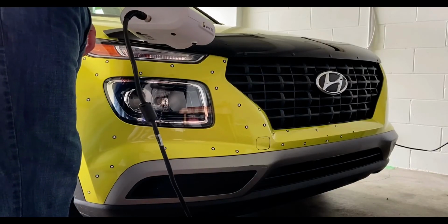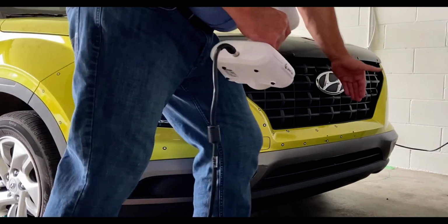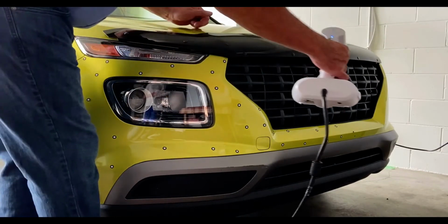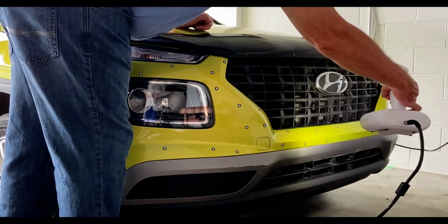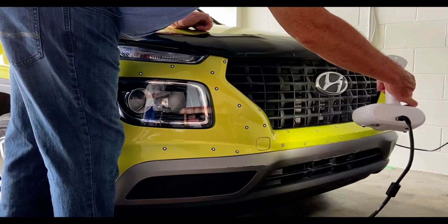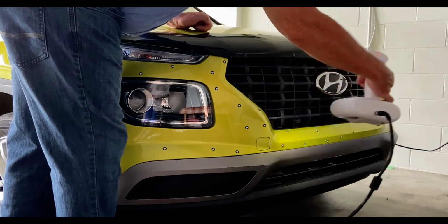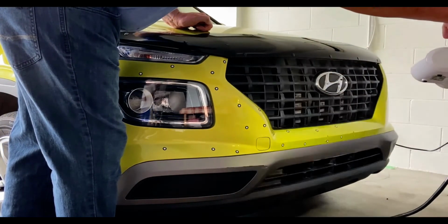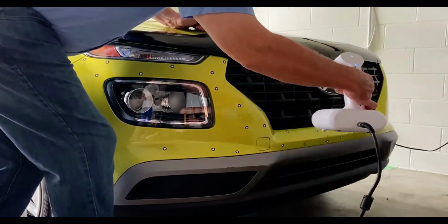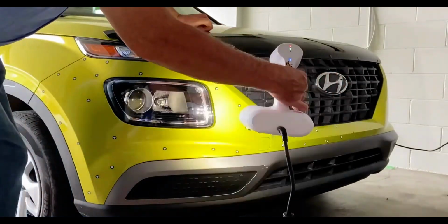We are now ready to begin the scanning process. We're going to start in the center of the bumper and make our way from the right to the left. We'll start by pulling the trigger on the scanner, and the emitter will give us a general direction of where the scanning is taking place. It is important not to scan too closely to your surface or scan too far, as we are demonstrating here. The optimal distance is about 30 centimeters from the object, and you want to keep the scanner in constant motion.